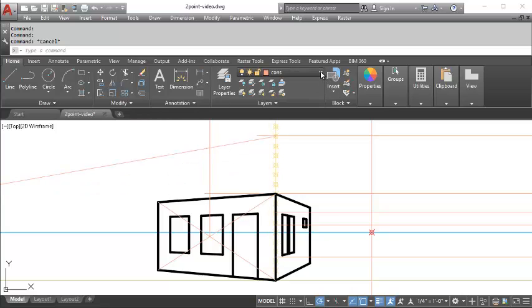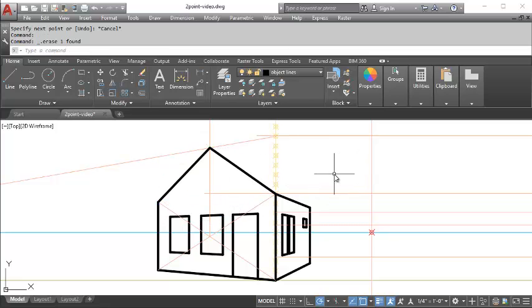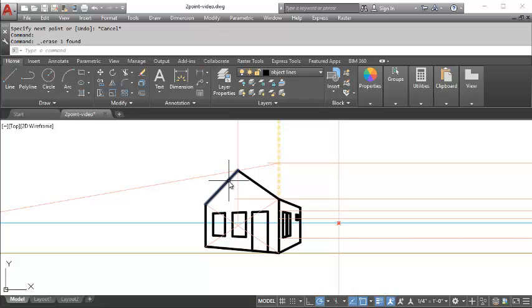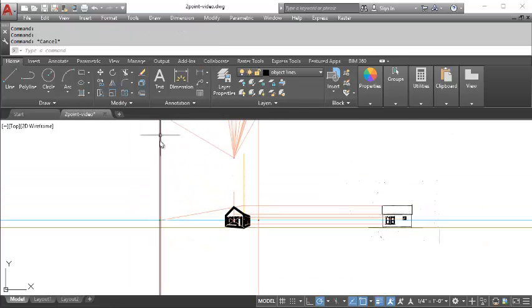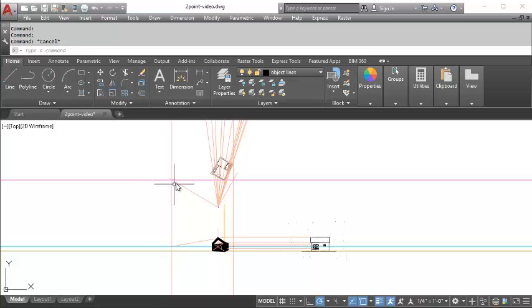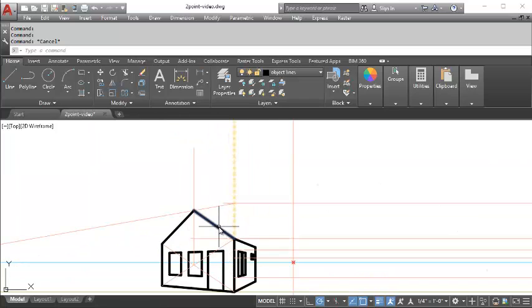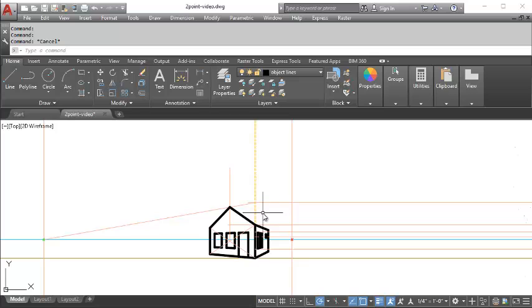So if I use the object lines layer and draw lines from that intersection to the edge of the wall, then I'm defining the gable end wall. And I can delete that line there. Now to get the other edge, we have to define the slopes in both directions. This slope has to be extended to the X line that we used to find our vanishing points from our picture plane. We can actually reuse it to help us draw things that are not parallel to the plane or the floor surface of what we're drawing this object on.